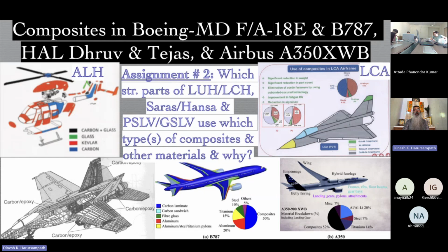You're also looking at some of the more complex things like the metal matrix composites, depending upon which stage of the engine, because as you know, at the fan stage and the compressor stage, the temperatures are still fairly low. In the combustion chamber, it becomes a little more. And in the turbine, it becomes even hotter because the entire combustion has taken place because of the fuel burn that has happened in the combustion chamber. And again, the temperatures in the nozzle are quite different.